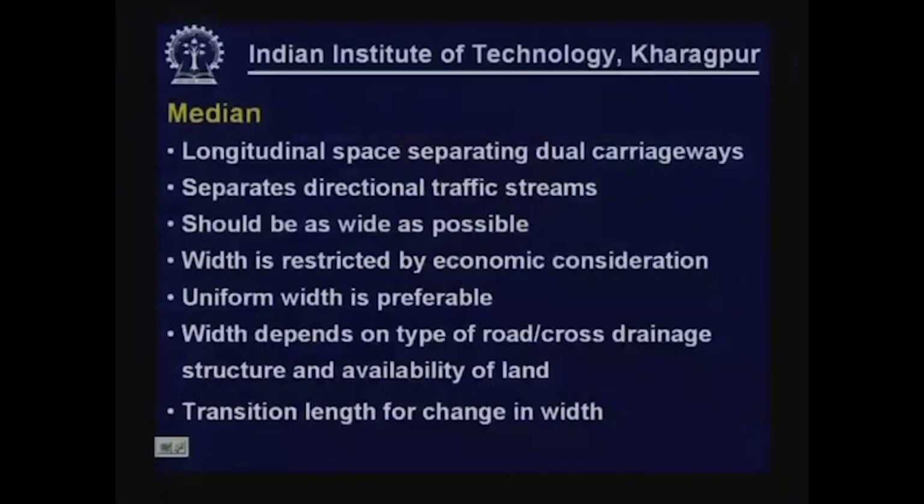So, wherever there is a change in width, it should be with adequate transition length. The width of the median also depends on whether it is a road or a cross drainage structure, depending on the type of facility, and also on the availability of land, to what extent the land is available for road construction.